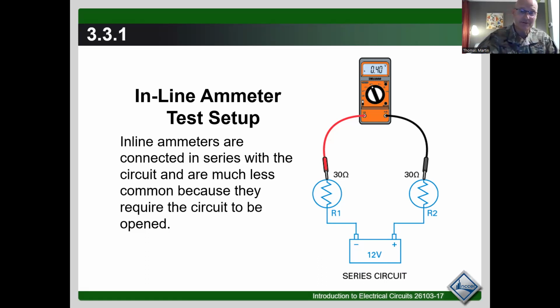These meters with the leads are for direct current, and there is a maximum ampacity, like 10 amps or so, I can't remember. If you take that selector lever and say, okay, I want amps, you best be testing something attached to a battery. If not, you're going to end up blowing the fuse inside the meter.